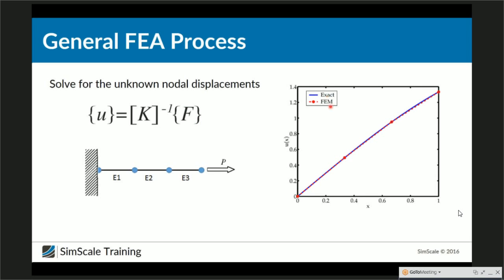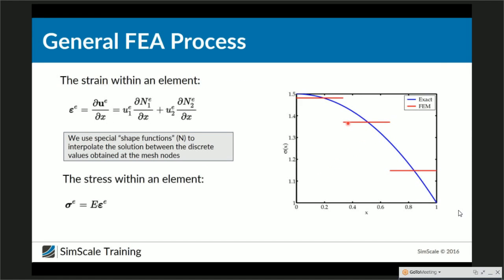We know the stiffness matrix, we know the force and load vector, and what we want to get is U, the nodal displacement vector, the solution of our simulation. And this can be really hard, because this nodal displacement vector is unknown, as I mentioned. And now we use numerical schemes and algorithms to solve U. And this kind of solution will look a little bit weird, because if we take a look, we can solve U by calculating the inverse of K multiplied with F.